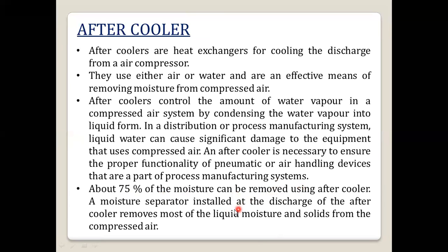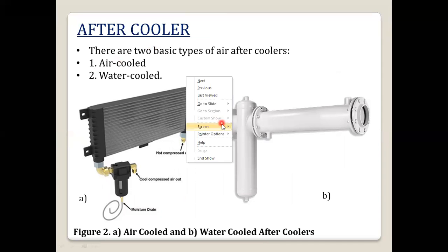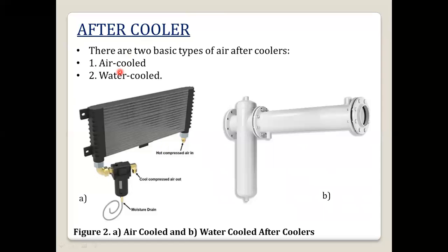So we are using the moisture separator, which is installed at the discharge of the after cooler. It removes most of the liquid moisture and solids from the compressed air. Normally we have two types of after cooler: air cooled and water cooled.